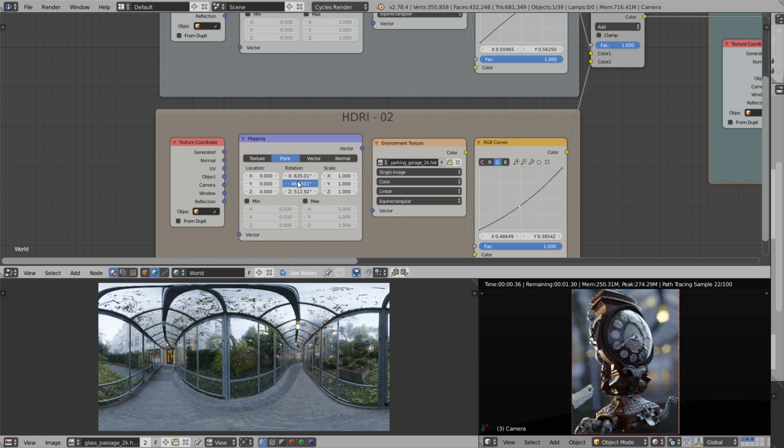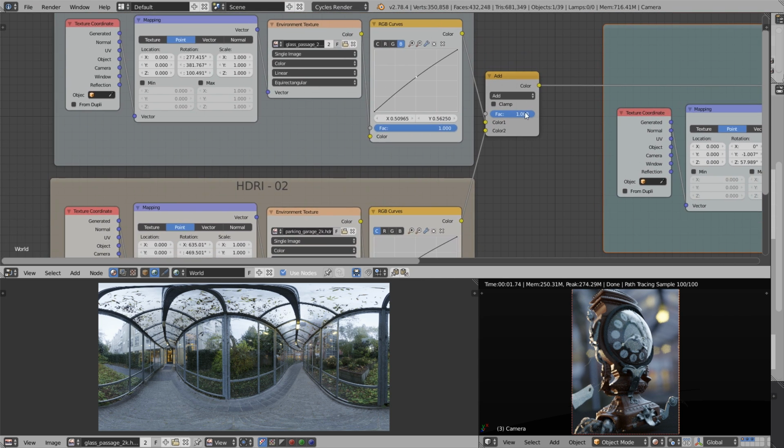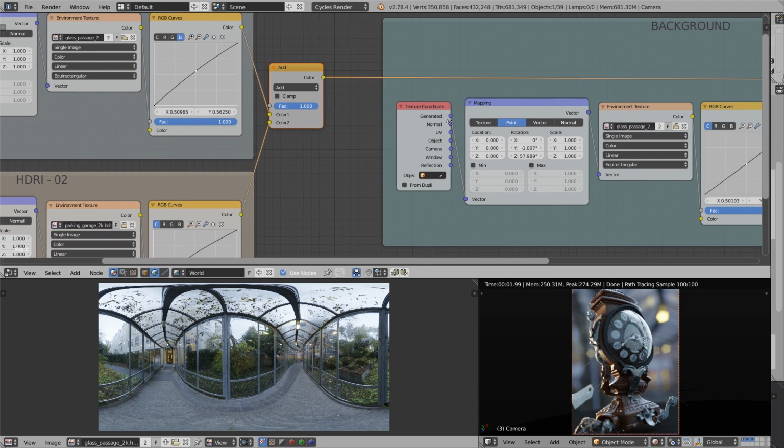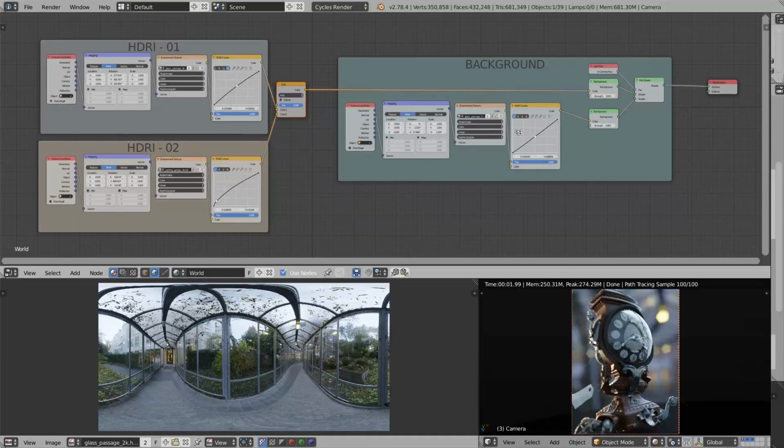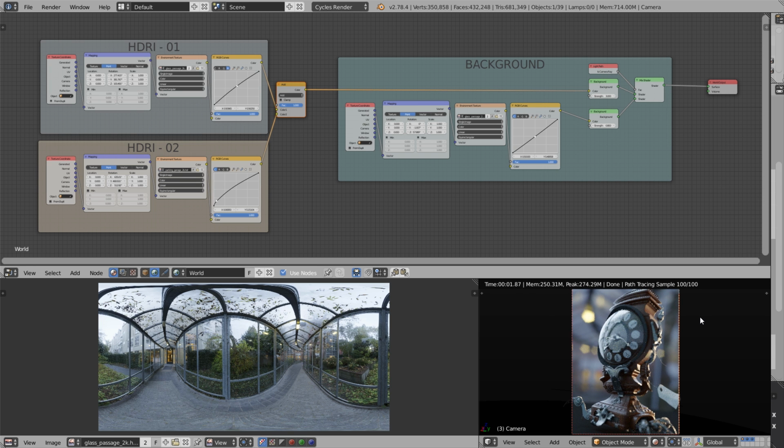And I wonder, have you noticed that this image-based workflow is basically going back and forth between rotating HDRIs and tweaking the colors? It's easy peasy, yeah? You just get into this flow and you tweak settings and you get amazing results. And of course, you can anytime go back to the add mode and fine-tune the amount in which these two HDRIs are mixed. Alternatively, you can press M to mute this node, press M to toggle it back again. And when you're satisfied with what you see, you can select the camera, press Ctrl M and X 2 times again to restore the original view of the camera.